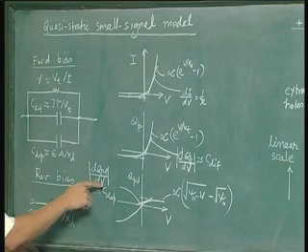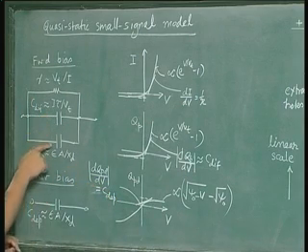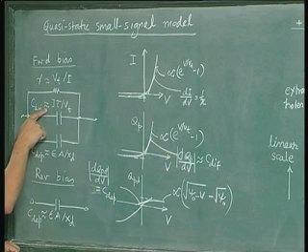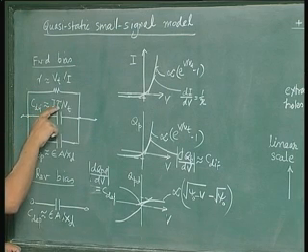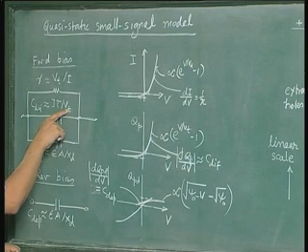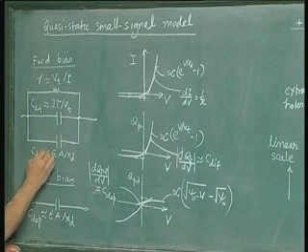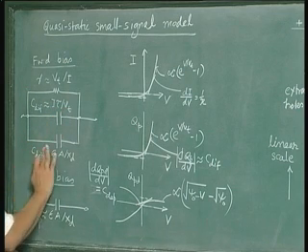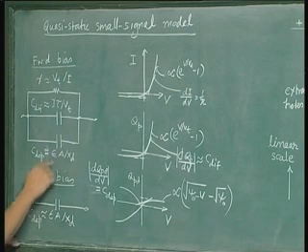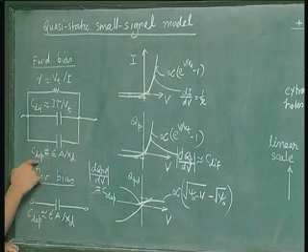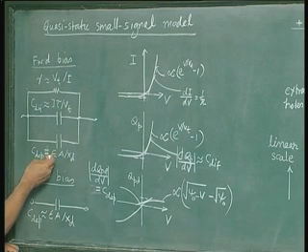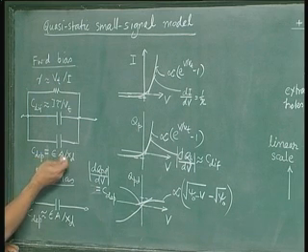So the depletion and diffusion capacitances are shown here. The results are that C diffusion is current times lifetime divided by thermal voltage, and depletion capacitance is equal to epsilon A by xd, where xd is the depletion width. The depletion capacitance can be seen physically as a parallel plate capacitor.